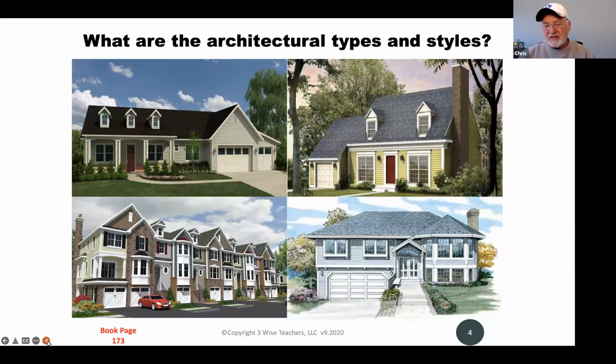As you move down, you see a 2-story home. What's interesting about this 2-story home is that part of it is above grade and part is below grade. On the right-hand side, as you're facing this, you see 2 stories, a downstairs and an upstairs. And then when you look over to the left, you see actually 1 story, where the garage is what we would refer to as below grade. On the right-hand side, we would call that above grade. Everything is actually built above grade, but on the left-hand side, below grade is defined by having any portion of the wall that actually touches earth. You can see that's the case here because it's an odd-shaped lot.